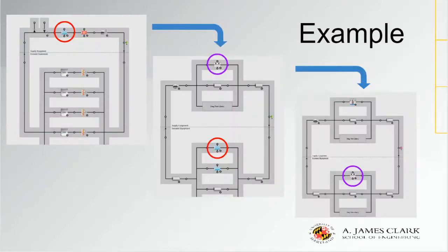To show you just how involved OpenStudio is, we wanted to show you an example. All the way on the left, you see a typical HVAC loop where you have the demand side, which is rooms that need to be heated or cooled, and the supply side, which is the equipment that heats or cools them. In the red circle is a cooling coil, which cools the air that goes to the rooms to cool them. In the next box over, that is another loop between the cooling coil and the chiller.